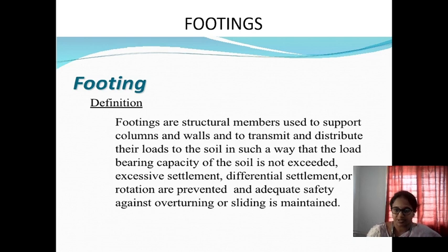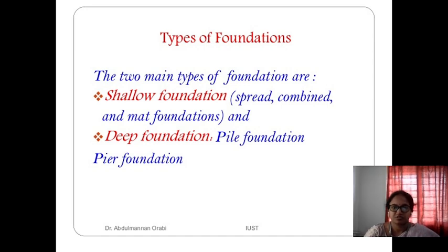Footings are the structural members used to support columns and walls and to transmit and distribute their loads to the soil in such a way that the load bearing capacity of the soil is not exceeded, excessive settlement, differential settlement or rotation are prevented, and adequate safety against overturning or sliding is maintained by these footings.